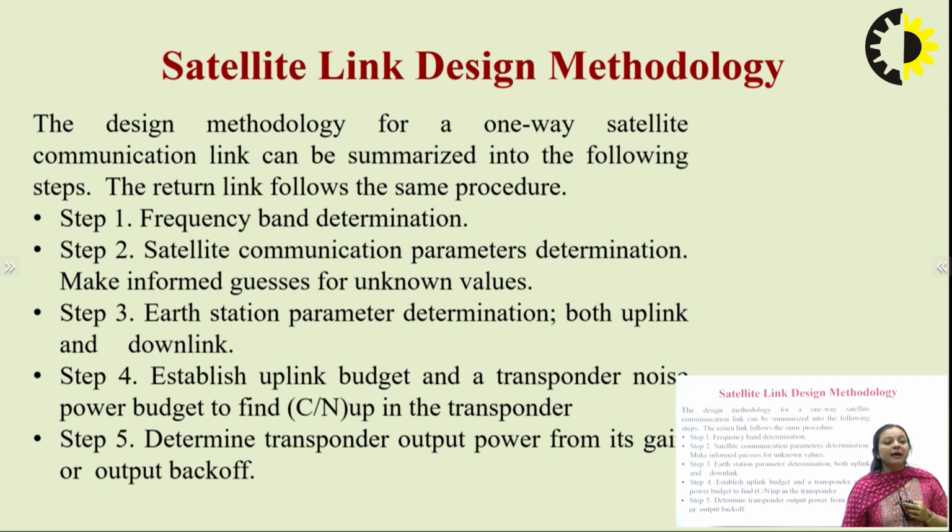Next is satellite communication parameters determination. Make informed guesses for the unknown values. You must know about every parameter. Then the earth station parameter determination, both uplink and downlink. Then establish a link budget, the uplink budget, because you're transmitting information from the earth station to the satellite. So I am concerned only about this link budget, that is from the station to the satellite. And a transponder noise power budget to find the carrier to noise power in the transponder. Then determine the transponder output power from its gain or output back off. Whatever the back off is in your output, you must first determine the transponder output power.